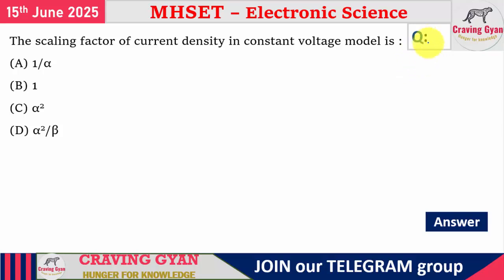In the fifth question, they are asking with respect to the scaling factor for current density. Current density is given by I divided by A. They are not asking general scaling, they are asking constant voltage scaling. In the case of constant voltage scaling, wherever you have the voltage parameter, you are not going to scale that parameter. You are going to take beta equal to 1 and then solve.